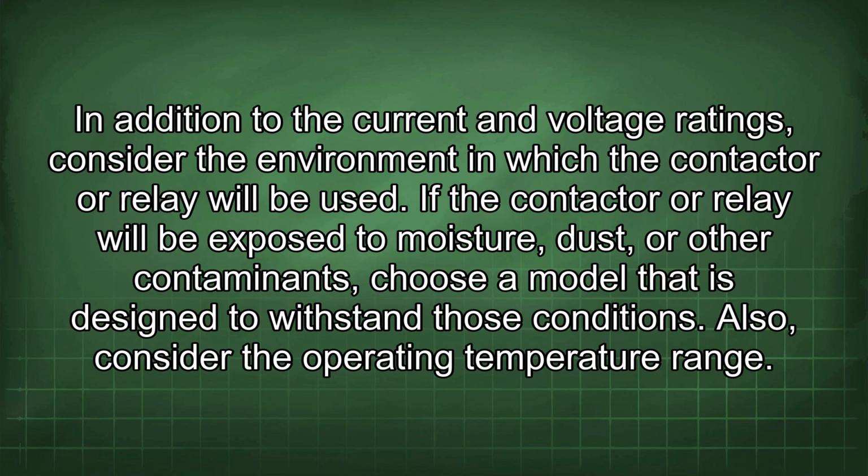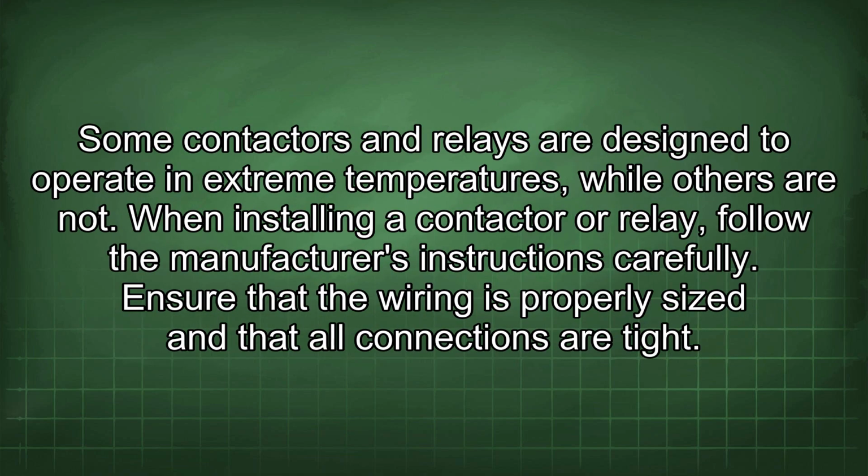In addition to the current and voltage ratings, consider the environment in which the contactor or relay will be used. If the contactor or relay will be exposed to moisture, dust, or other contaminants, choose a model that is designed to withstand those conditions. Also, consider the operating temperature range. Some contactors and relays are designed to operate in extreme temperatures, while others are not.